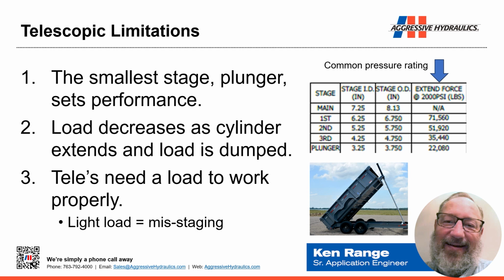In other words, in a dump body application that's common to telescopic cylinders, as that dump body extends up and the angle increases, the load is dumped and the cylinder load decreases. And so we have, with some customers, actually calculated the load loss at various stages in that process to make sure that each stage is capable of doing its work depending on its stroke.